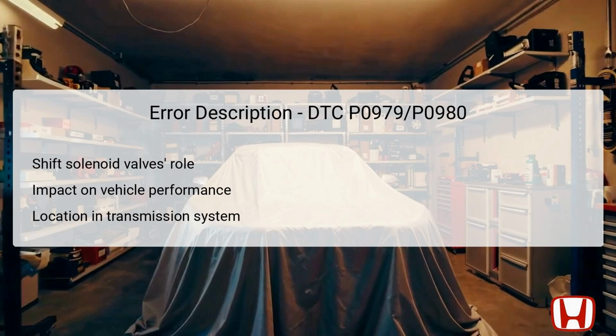Located within the hydraulic control unit of the transmission, these solenoids operate based on electronic signals from the Transmission Control Module, TCM. When the TCM detects issues with the input-output of these solenoids, such as low or high inputs, cases represented by DTC P0979 and P0980, it flags these as diagnostic trouble codes.